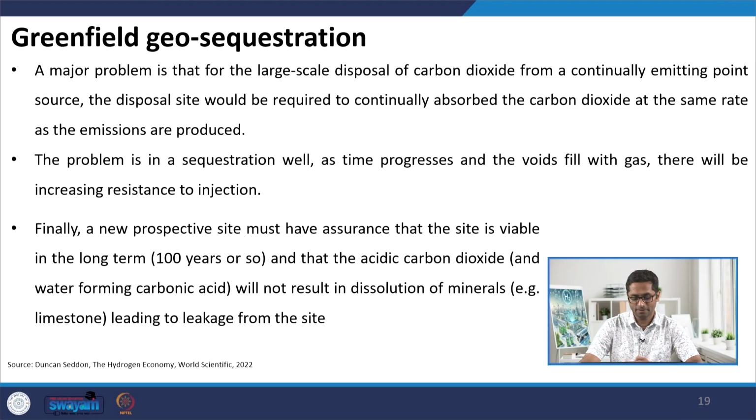Further, it is also expected that as time progresses, the voids are going to fill up with gases and there is going to be an increased resistance to injection. Further, we also need to be pretty sure that the CO2 is going to remain there for quite a long time, roughly 100 years or more, and also be careful that any carbonic acids or carbon-based chemicals that are being formed do not leak out and cause other problems in the water table.